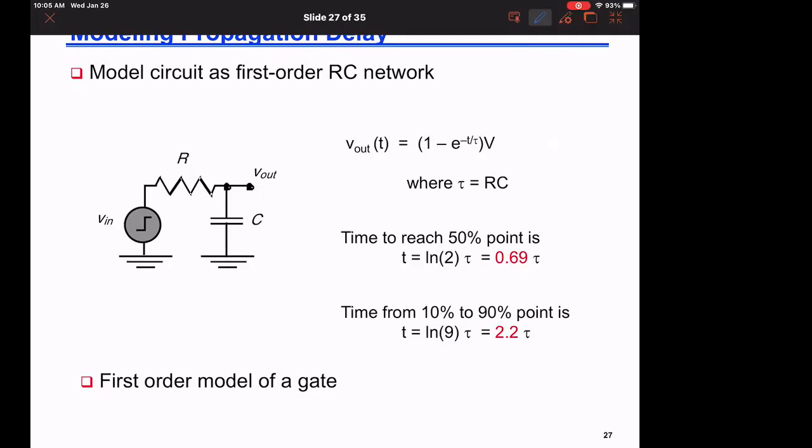I have to define what my initial conditions at the output are. So Vout will have an initial voltage. This initial voltage is supposed to have been either given to me or I detected from the input initial state. So Vinitial at the output here is 0.